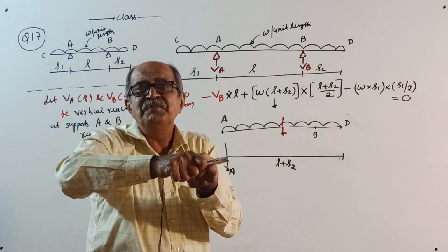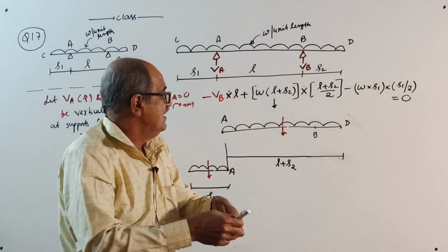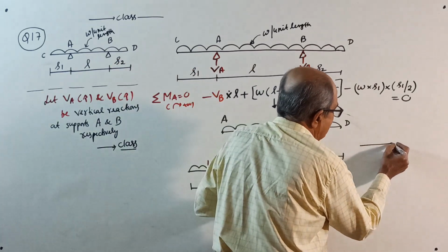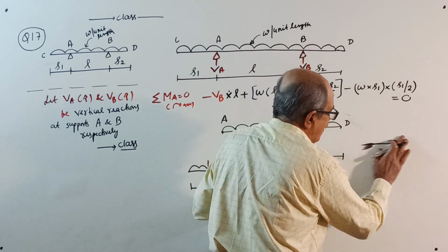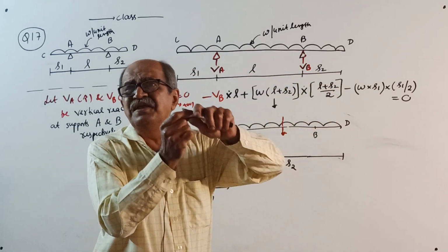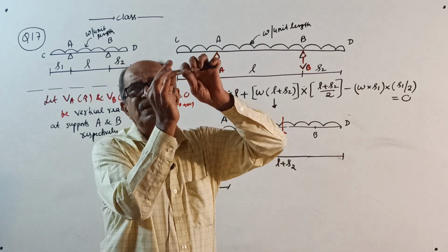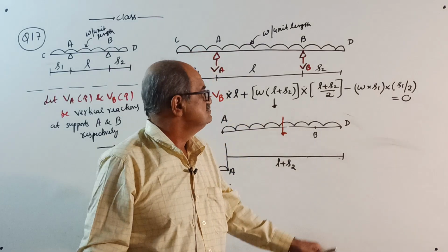You can prevent lift in two ways. One of them, put a support here, if lifting is observed, put a support like this. Or you provide a hinged support. If hinged support is there, if you apply downward load, upward reaction; apply upward load, downward reaction.